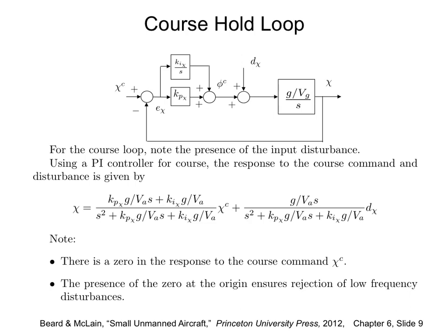The coarse loop is the outer loop. If you remember, to change course, phi is what goes in. To control the yaw of the aircraft, you need to roll. So what should the roll be such that I get a desired yaw angle? Right now the course is 0, for example, and you want to go to chi c equals 45 degrees north. How much should you roll? You roll until you get your 45 degrees. That's the objective here.